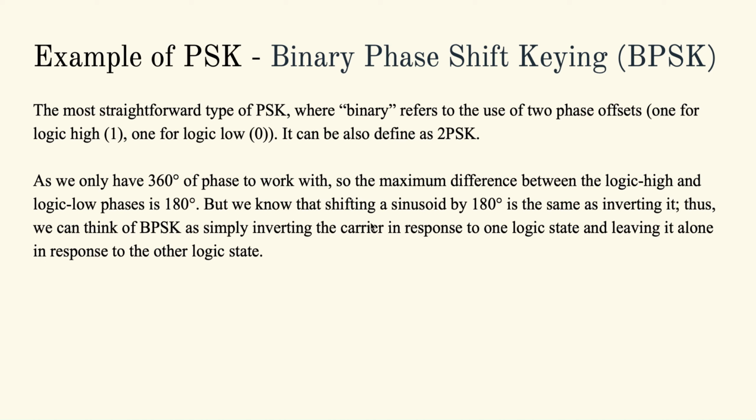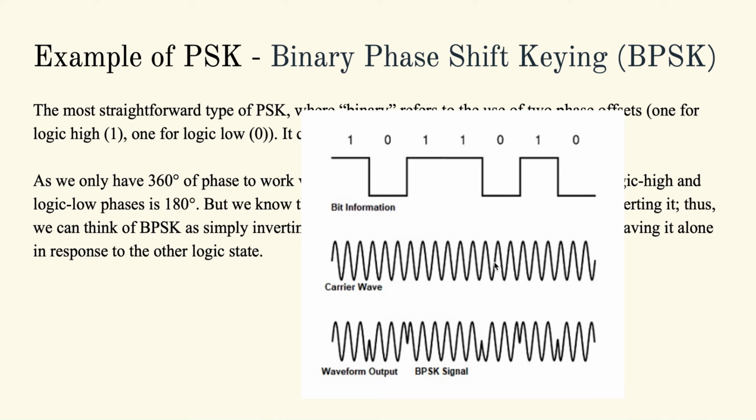We do know that shifting the phase by 180 degrees is equal to inverting the data. So we can think of BPSK as simply inverting the carrier response for one logic state and leaving it alone at the other logic state. Here is an example. By converting 1 to 0 with the carrier wave, the output waveform will be inverted, leaving the other state as it is. Another example is converting 1 to 0, also the same; you can see the output waveform is inverted.